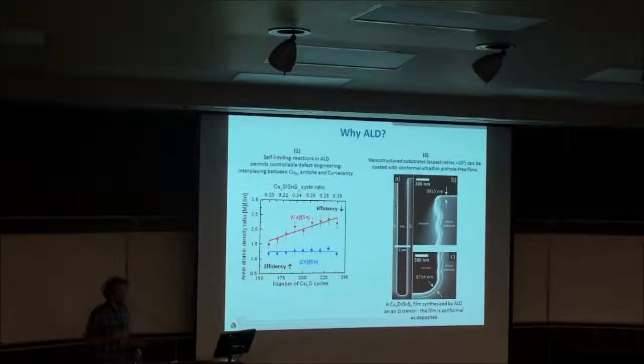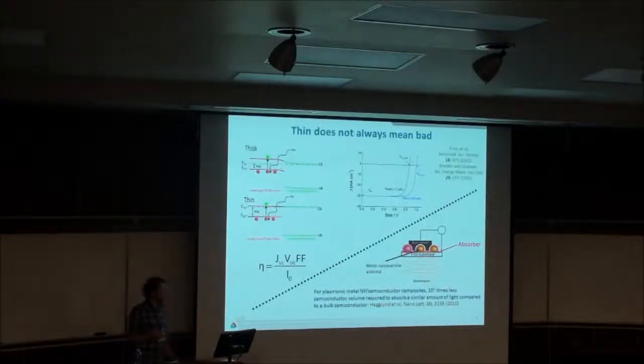So, of course, growing very thick layers, like was also shown, approximately 500 nanometers or even 1 micron, is very hard for ALD because it's basically 100 nanometers, and sometimes it takes 24 hours. But the point is that thick solar cell films don't always mean it's good.